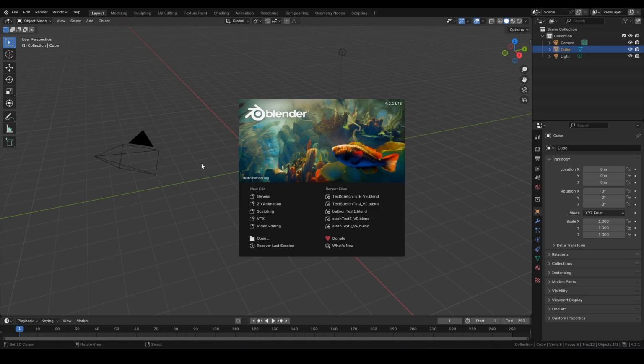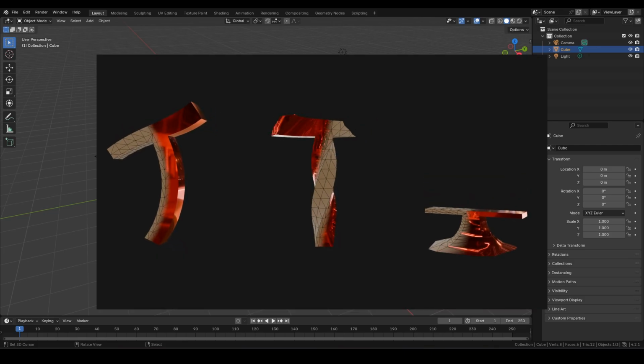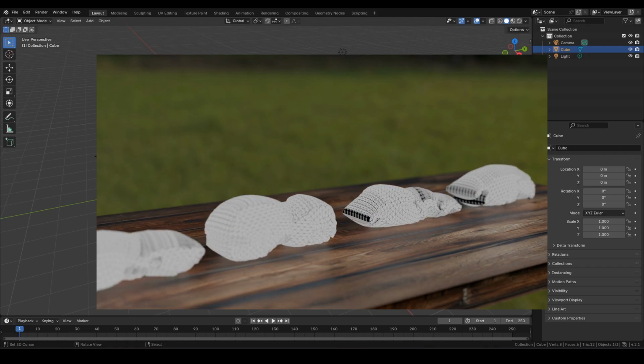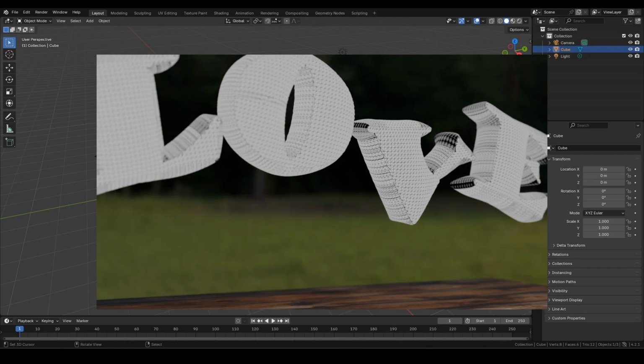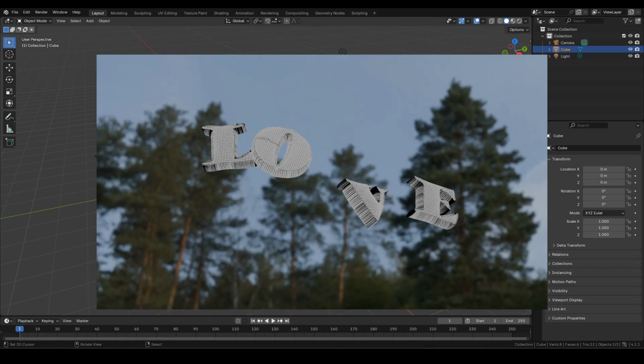So, before touching the node tree, let me explain why remeshing is required for 3D text effects. First off, remeshing is not quite necessary if your 3D text animation only requires simple operation like translation, rotation, and scaling. However, remeshing is needed if you want to 1. Add deformation like bend, twist, squash as a part of effect, or 2. Use simulation like soft body and cloth.